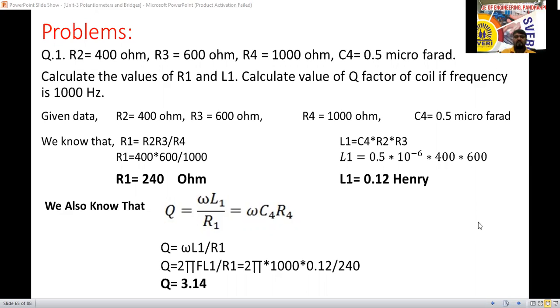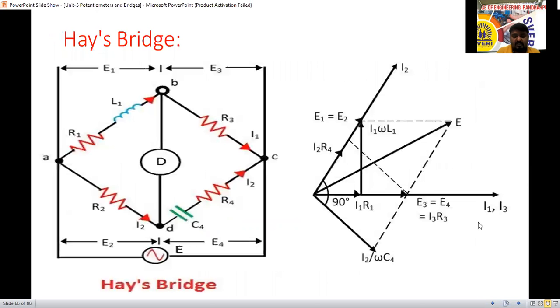Okay, so it completes the Maxwell bridges, both inductance and capacitance bridges. So now we'll go for the Hay bridge. Actually, it is also similar, an advanced form of Wheatstone bridge only. Advanced form of Maxwell bridge it is now. The Maxwell bridge is for medium quality factors less than 10, but for quality factors of more than 10, we are going to use this Hay bridge.